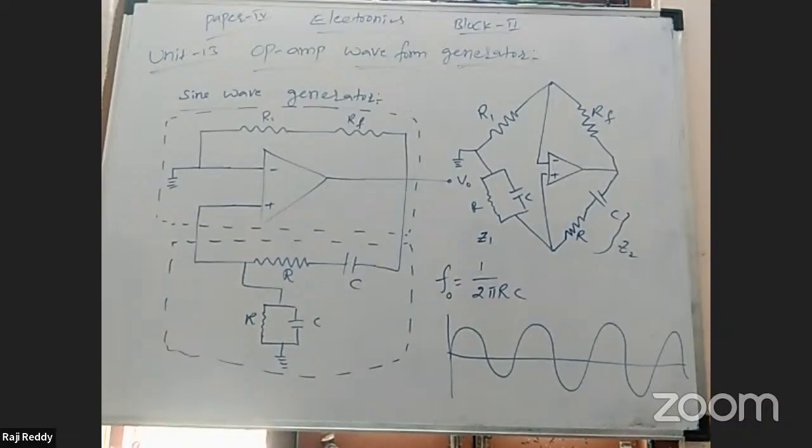For the two amplifiers, the input resistance and feedback resistance can be split into two branches. In one branch, in the feedback resistance place, you can take a capacitor. In the other, you can take a resistance. Then the square wave can be converted into a triangular shape wave, nothing but a triangular wave.